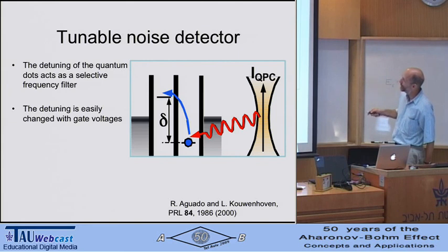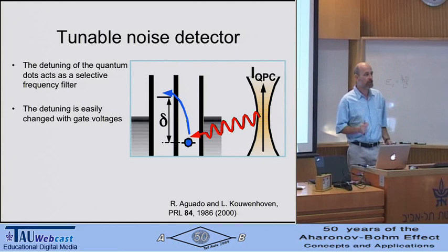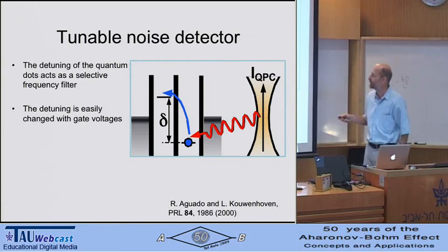The detector emits a photon. The photon hits the electron in the ground state. The electron goes to the excited state. It may leave the system and is replaced by an electron from the right drain contact. So basically, by exciting this electron by a single photon, we have effectively transported one electron from right to left.